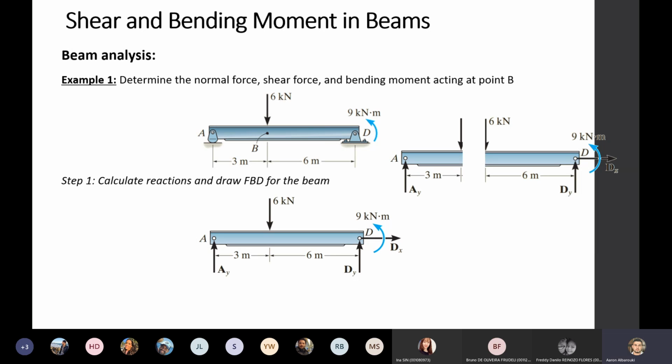And the rule about the positive direction tells you that to be able to add the shear force in positive direction, that should rotate the portion or the segment of the beam clockwise. In this instance here, because I'm adding shear force on the right hand side, that means it should be down. In this instance here, shear force on left hand side, up. All good? Okay, so always looking to move in the clockwise direction. Exactly. Always trying to rotate this segment or that segment in the clockwise direction. Okay, cool. Thank you.